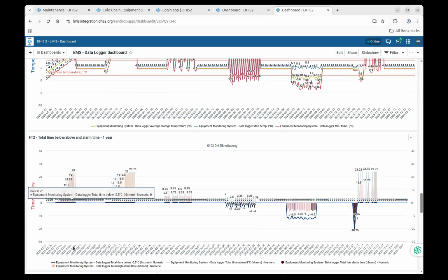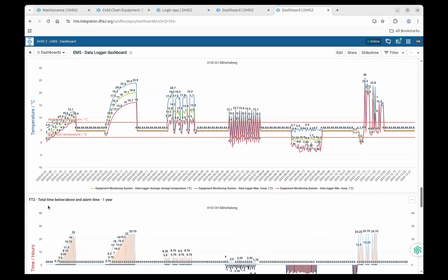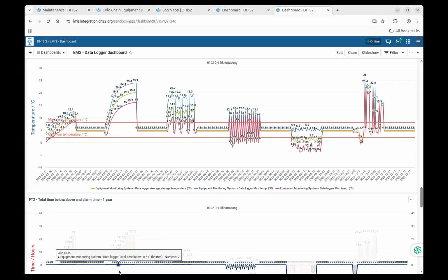alarm times in hours, and it has a pattern, and patterns are very good for machine learning. Basically, feed the data into a bespoke machine learning program, and then the AI will indicate one, two, or three possible reasons for repairs and help guide the cold chain technician, the engineer, maybe even the storekeeper on what the possible reasons are. If there's a quick fix, like maybe cleaning the gasket, or cleaning the ventilation opening, is something that anybody can do, but maybe you don't think of it.